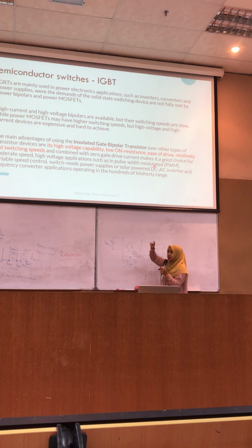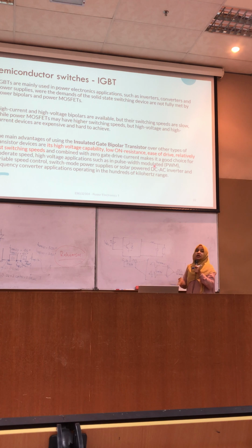So this inverter is actually a connection of switches. In this case, let's say this is a three-phase system. So you will have a three-phase inverter, so you have 6 switches inside here, but I only represent it as one. So there are 6 switches that will be connected for this three-phase system. And then you have your filter, which is a second order low pass LC filter. And then this is your load. Your load, you can have R load, you can have inductive load, and any type of load, no problem.